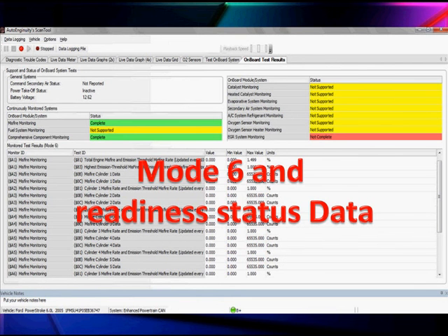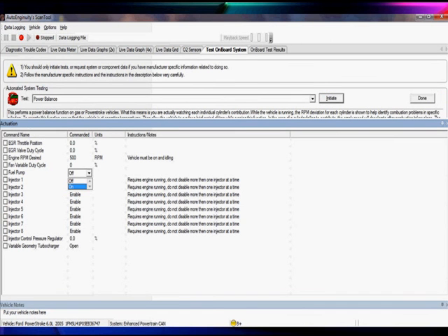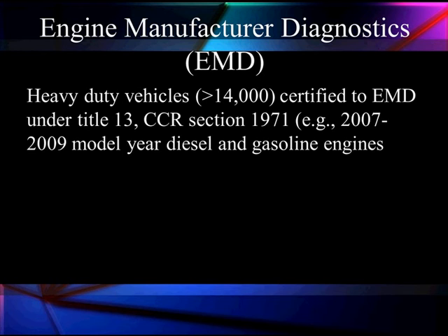You notice a lot of yellow things that are not supported. We do only a few things with a diesel, but they're a very valuable, useful piece of information we need to understand. We're going to use bidirectional testing. Here we're taking individual injectors and we're turning them off and on, and we're controlling individual injectors. We can also do power balance and all sorts of various other things.